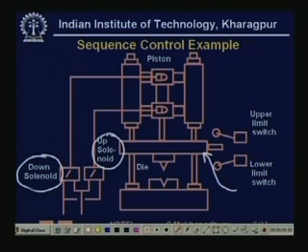So, these are hydraulic presses. If the up solenoid is energized, then the pressurized fluid flows through this path and goes into the machine. So, the machine is constructed in such a manner that this press goes up.